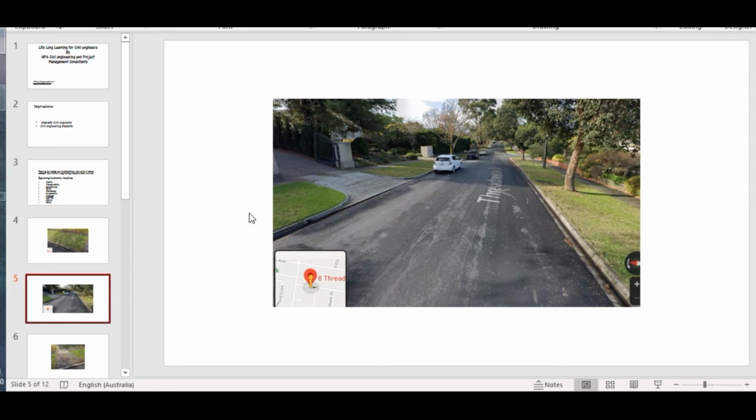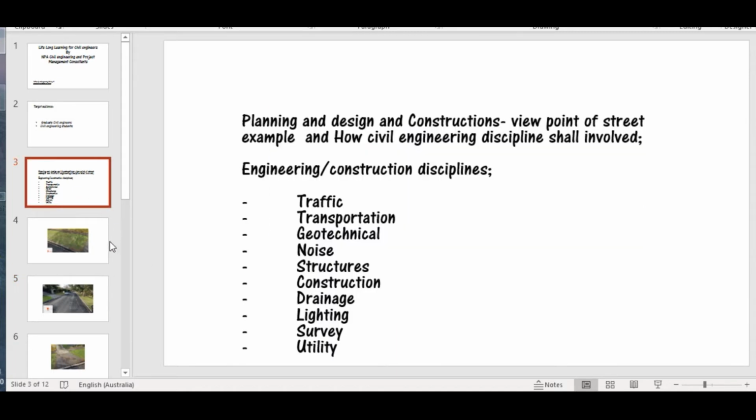And there are a lot of sophisticated tools and techniques you might have studied in civil engineering. All this is to create a basic scenario, and then going into detail on how the growth will be anticipated using that scenario, and developing a model using a provided industry-based model, and coming up with a growth rate and density in terms of ADT for the street, and deciding capacity and lanes using the appropriate standard based on your country. So this is the traffic part we just talked about.